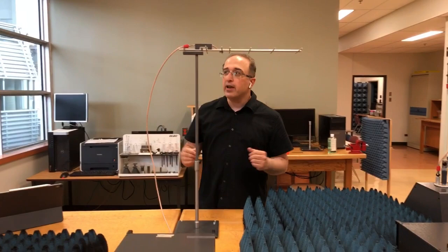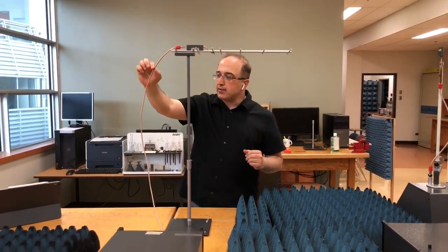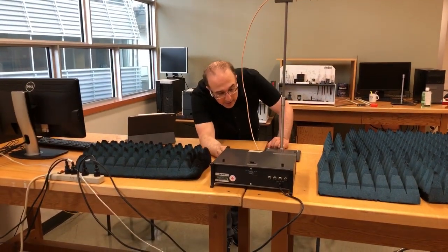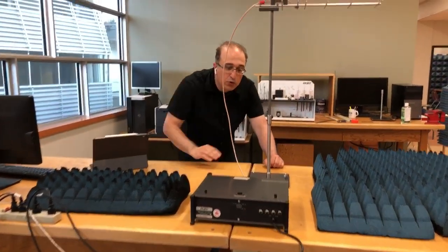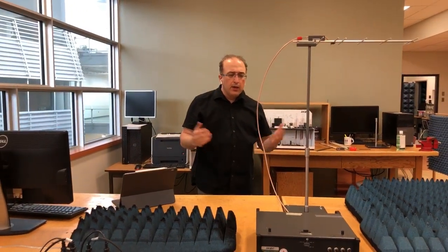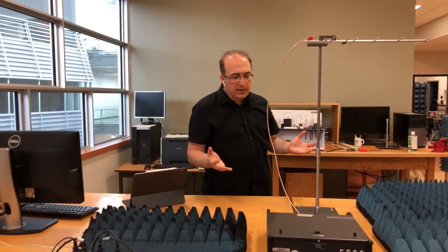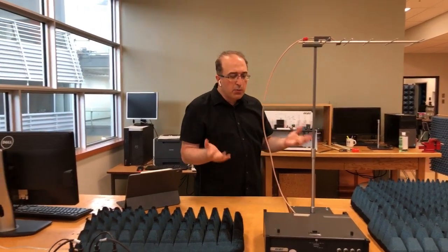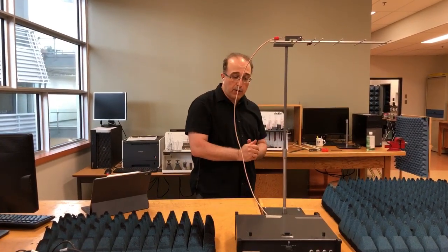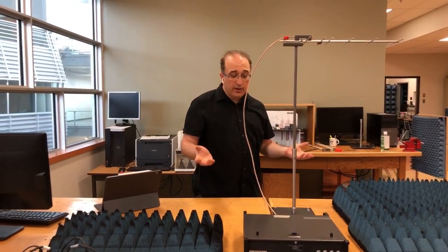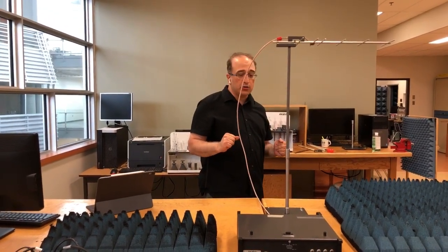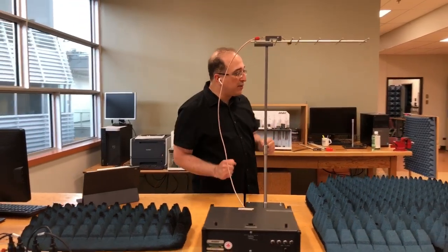It does not move. This Yagi-Uda antenna is connected with this cable to the RF generator. Now, this RF generator consists of 2 frequencies, 1 gigahertz and 10 gigahertz. So this essentially provides the RF signal for us. For example, in some labs, we might be measuring at 1 gigahertz, then we turn on the 1 gigahertz oscillator, and in other labs, we might be using 10 gigahertz, then we're going to turn on the 10 gigahertz oscillator. So these are the 2 components that we have on this side.